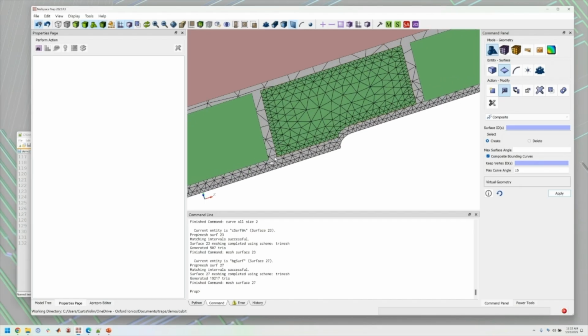For those of you who are familiar with the gapless approximation, it leverages the fact that when these gaps are 0 microns wide, the actual charge distribution is an impulse, right? It's just a line charge around the perimeter of this electrode. And so then it just integrates along those line charges to get the potential and electric fields above the trap. In our case, these gaps have some width to it, and so this charge is not a line charge. It's sort of blurred out a little bit, but it's still essentially a line charge.